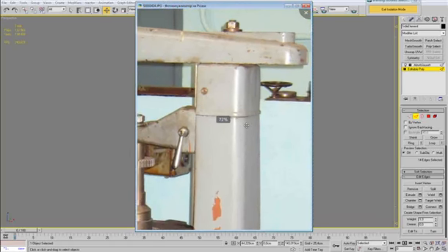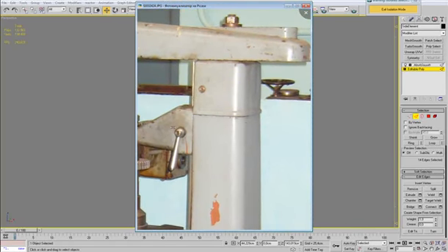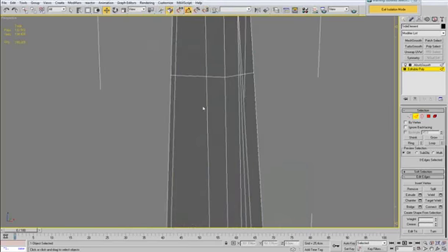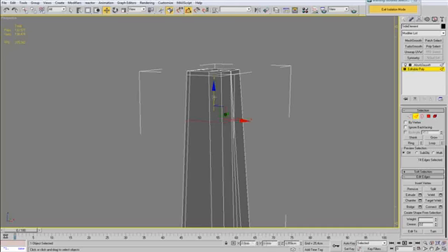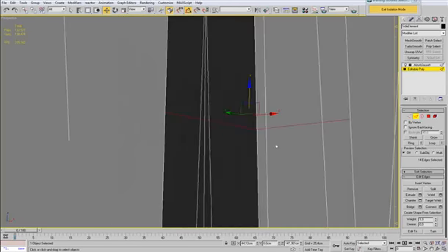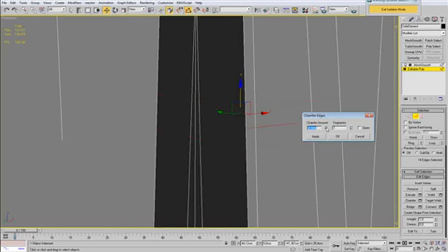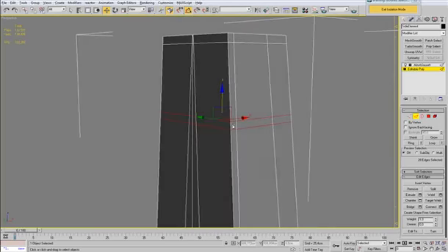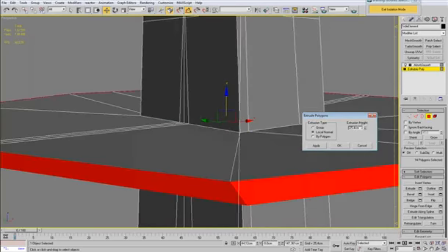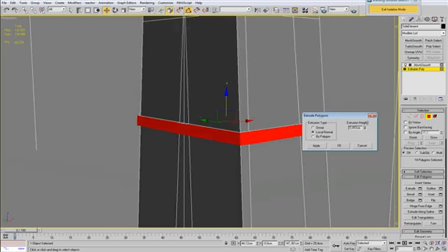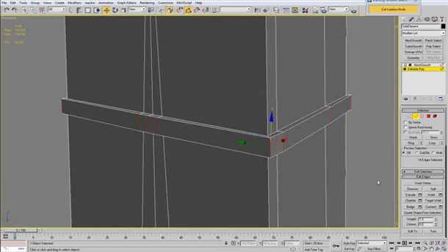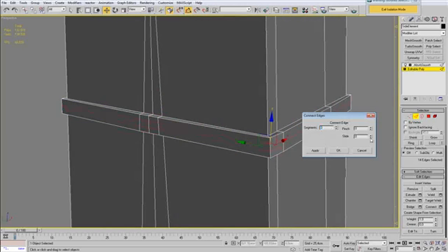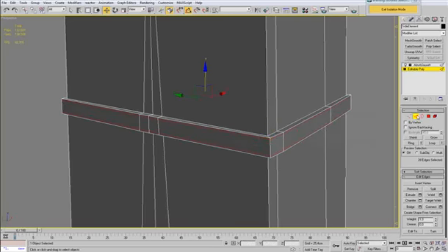So again, connect, position it properly, use the chamfer just to double the edge, ring select those edges in between, control click on the polygon mode, turns the selection to polygons, extrude them by local normal, and again connect two segments and pinch them up.